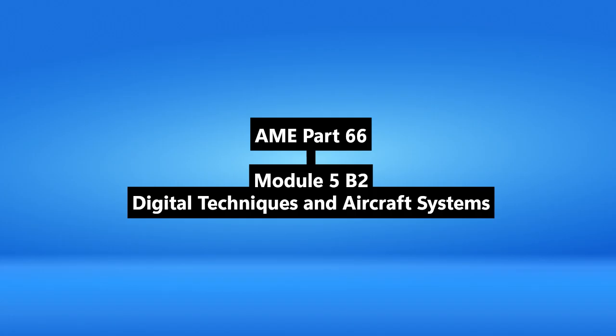And fly-by-wire? And cabin systems. Yep. Fly-by-wire replaces heavy mechanical cables and pulleys with electrical signals to control flight surfaces. And cabin systems, in-flight entertainment, Wi-Fi, even onboard cell phone capability via satellite links, SATCOM. These use sophisticated servers, communication managers, and often high-speed data buses like FireWire or Ethernet running through the cabin. It's all interconnected. That's an incredible range of systems, all relying on the digital and electronic principles we've discussed.